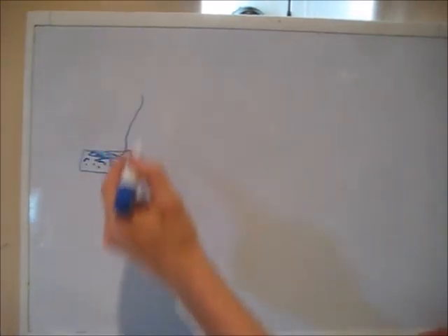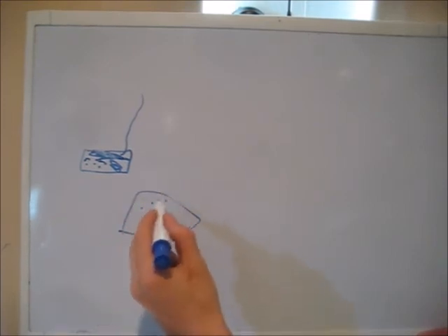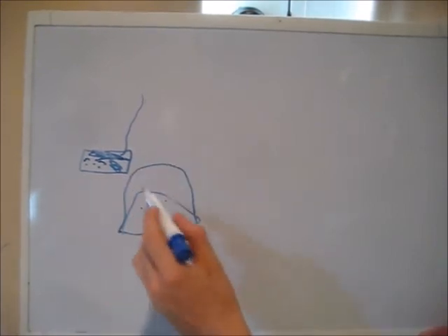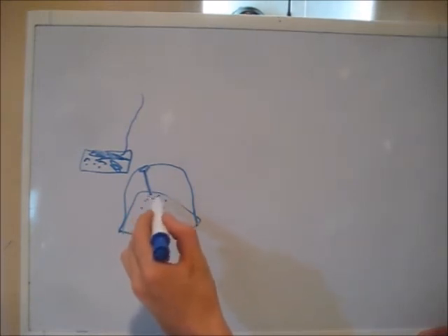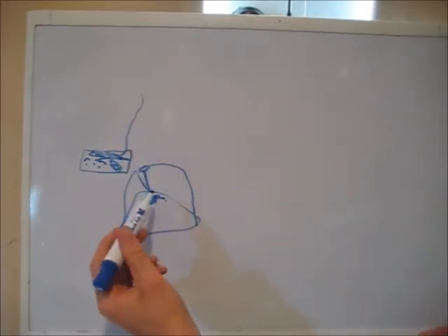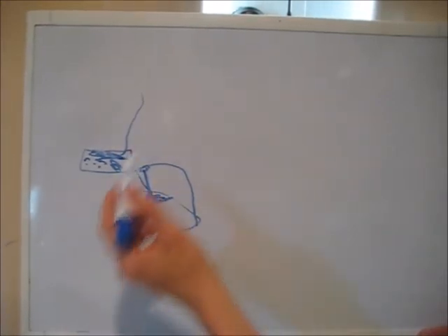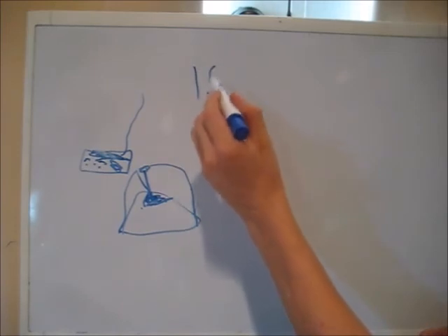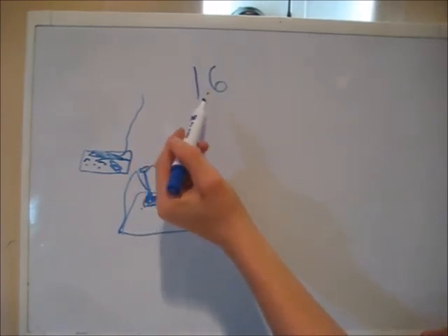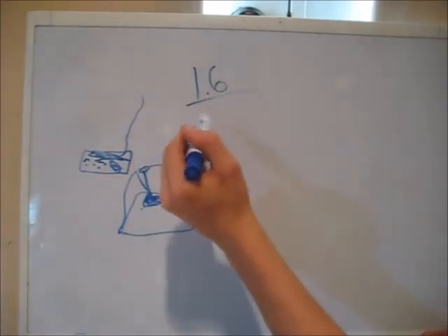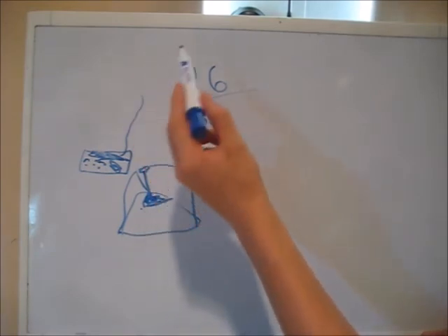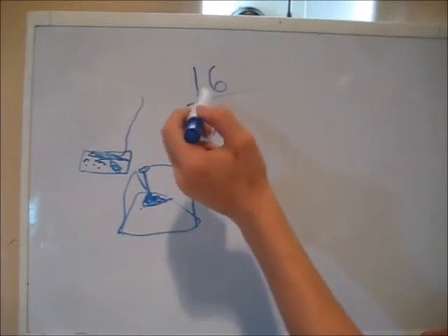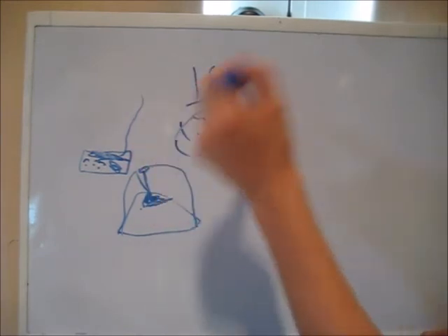The problem is, inside this radio, there are little finals inside the back of this radio where the antenna comes in, and where your signal is processed, there's little finals in there. And that's kind of where your signal is processed and it's sent out to go be radiated to the world. These can be damaged if your SWR is higher than approximately 1.6 continuously. So that's my picky number. I try and always keep my antennas below 1.3. Now, some people say as long as it's below 1.9 you're okay, but I try and keep it around 1.3.